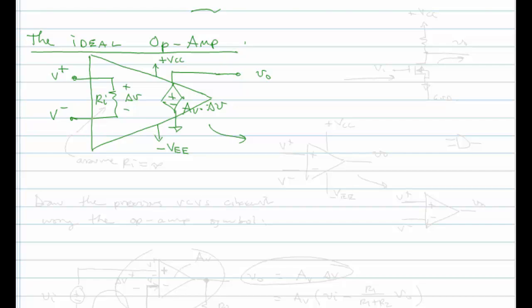You think of the NMOS amplifier, right? You have a VI, you have a VO, but there is power. There's VCC coming in, and there's ground, right, down here. And so even though when we think of the signal path, we think, oh, we come in this end, and it comes out here, and we can kind of forget about VCC being part of it, but we know in the end that there has to be a power source to be able to achieve this kind of amplification.